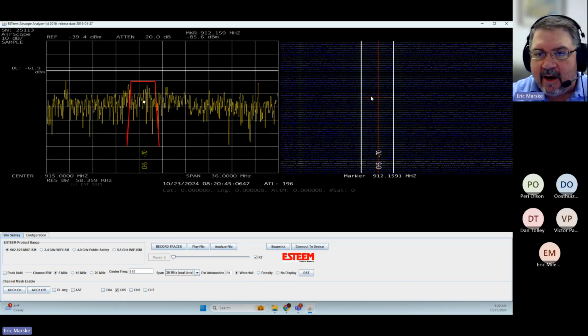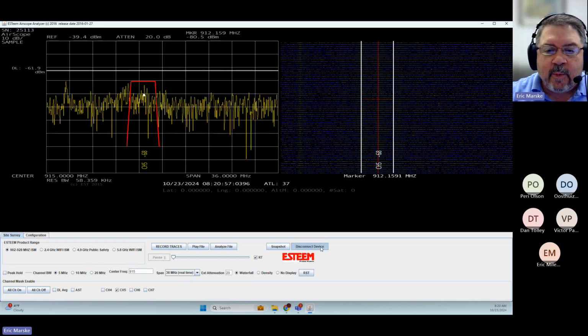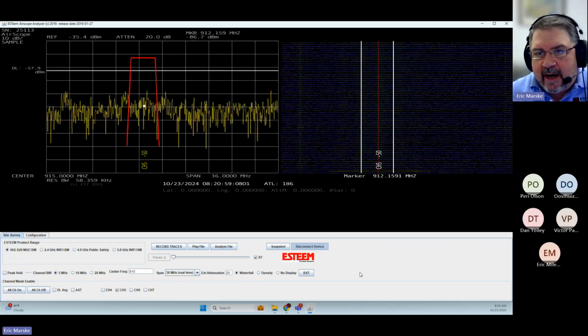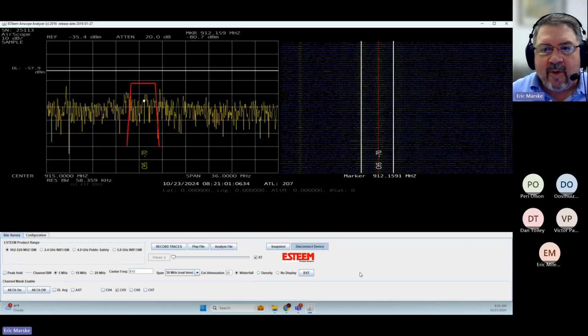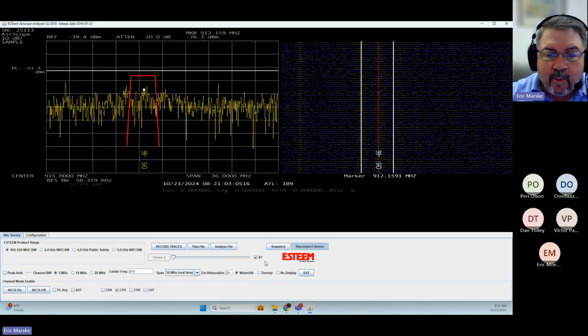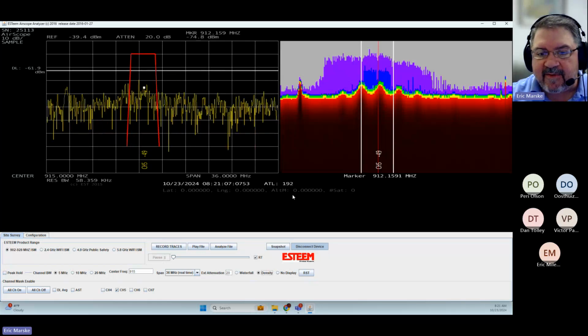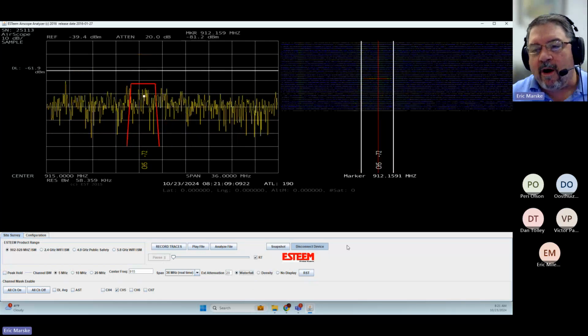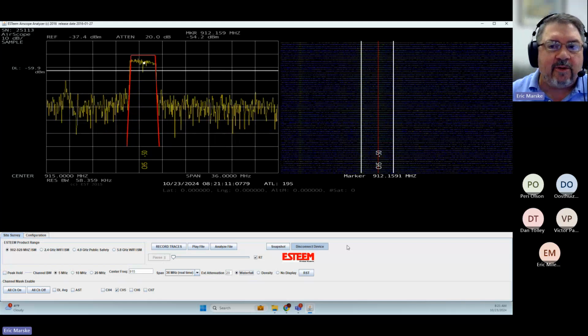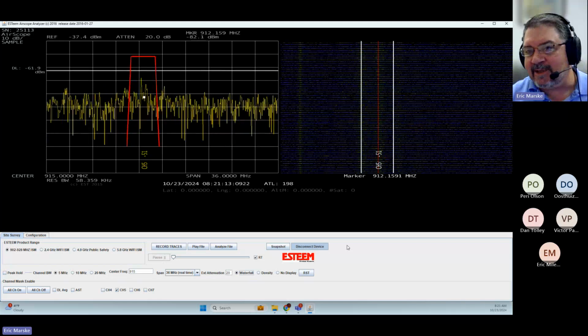But as you can see here, we can identify there is one single packet that is operating on here. It's going to be very difficult for you to see because my display is actually going to be running so much faster. But as we look at this occurring over time, we can see, yes, we certainly have a transmitter operating on channel number 5, but looking at it on the waterfall map, it's actually only coming and transmitting a couple times a second.